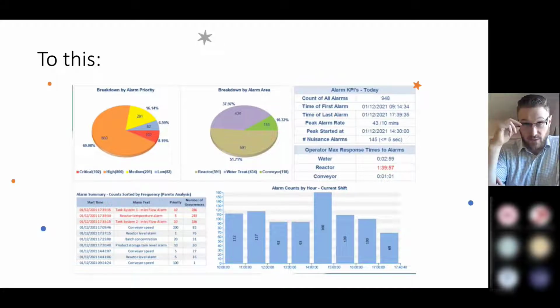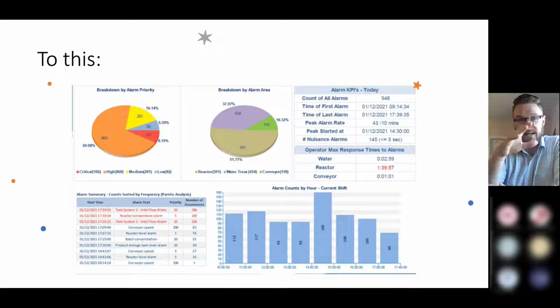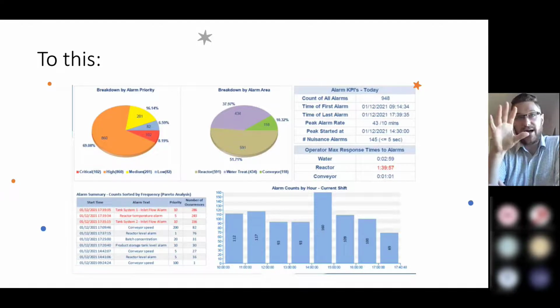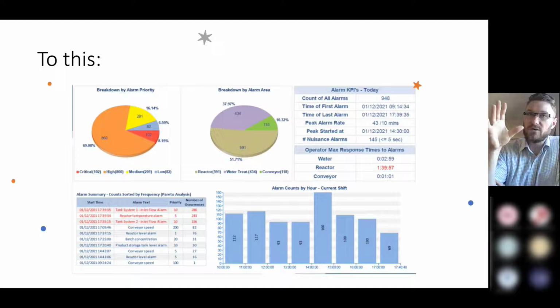your machine. And so you can see here that they've got an enormous, let's say 300, and then another 250, and another 150, so 300 plus 400 approximately. So up something like 700 out of 1,000 of those alarms are caused by these three primary alarms. And so by using AVEVA Reports, you can potentially change or optimize or improve the readability of some